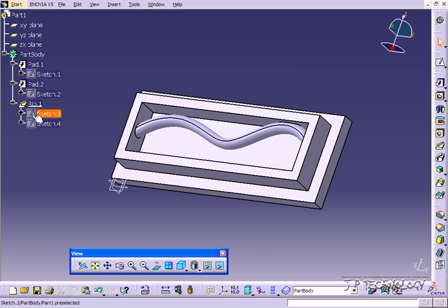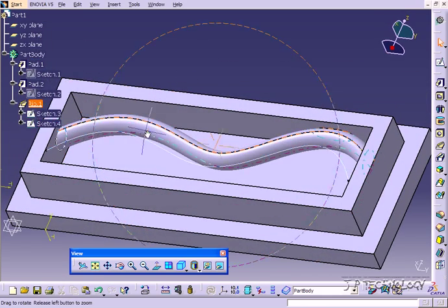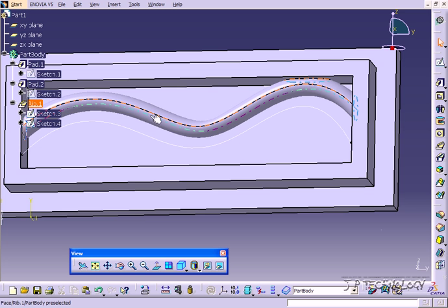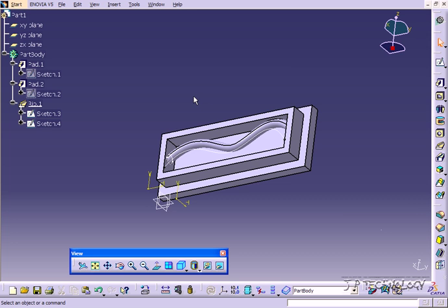Now open up the rib and let's show the sketches that we've been using. And if you notice, this line here is not actually touching the rib that we've cut out. So the sketch that you've made is going to automatically shift up or down to wherever the profile you're going to use is. So as you can see, this has been shifted up to meet this profile and then follows that curve. So all you need to use the rib is a profile and a path sketch to follow along with. So you're going to need two sketches to use this tool.